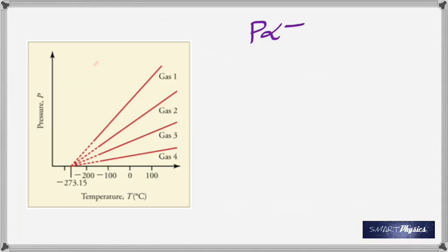Anyway, you drive. So as you drive, what's happening to the temperature of the tires? Increasing, right? Come on, we're talking about the tires. It cannot expand. It's negligible expansion, right? So the air inside is trapped. The volume cannot change. Even if it changes, it's negligible. So what happens to the pressure? Goes up. So what was the constant here?